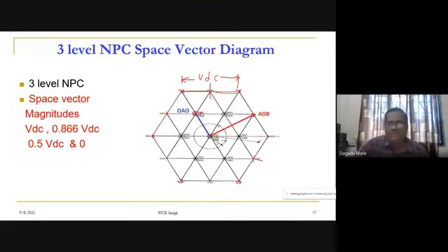One is the outer hexagon, where each crossing will have a unique switching state. But in the inner hexagon, each switching state is represented, for example, as BOB or BAO, or AAO or OOB.